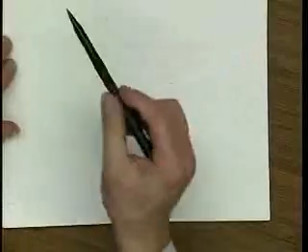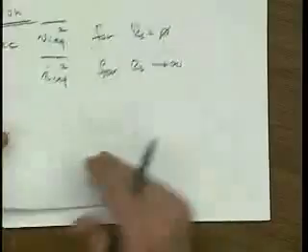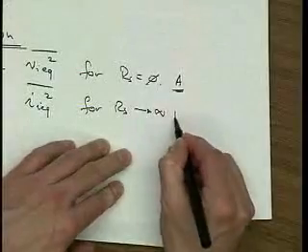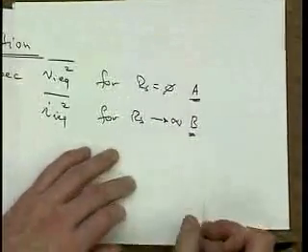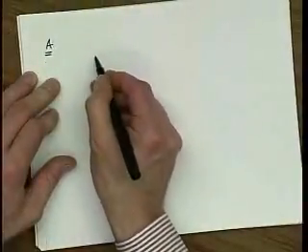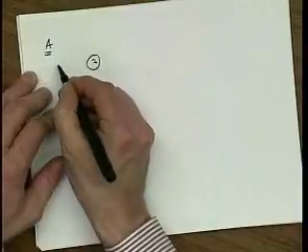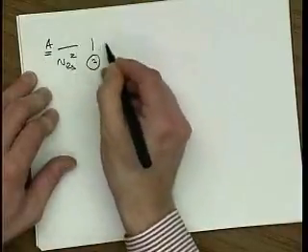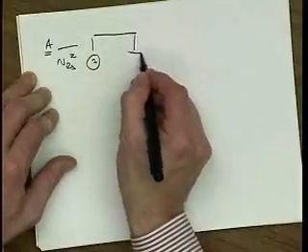You have seen this before. Okay, so well, let me just sketch the concept. We will split up the circuit into what I usually call case A and case B, and I calculate them separately. So in case A, I make RS equal to 0. So if my input I set that to 0, I have VRS squared, RS is now 0, goes on to CL.